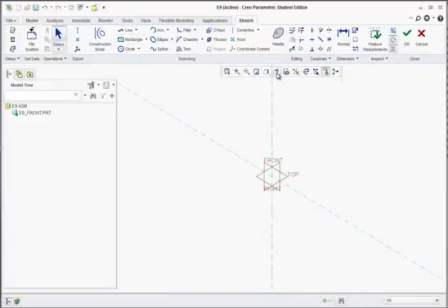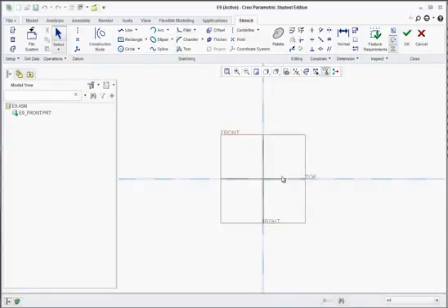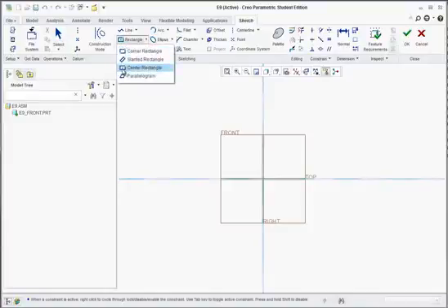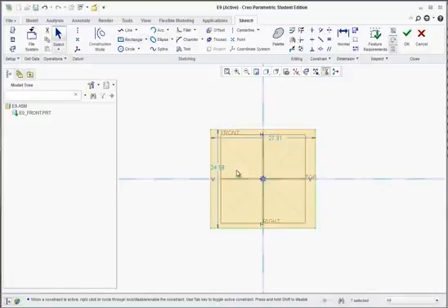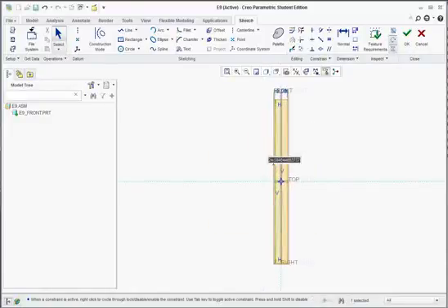We'll zoom up to it, and actually we'll go to AB front, and we'll draw the front of our sketch here. So go to rectangle and find center rectangle. Click on the origin and drag out a rectangle, and try and get it towards equal on both sides. I don't seem to be getting it, but that's okay. Just click it out as best as you can. If you get equal lengths, then you're in good shape. But this will work too. So we'll go 2 inches by 2 inches.